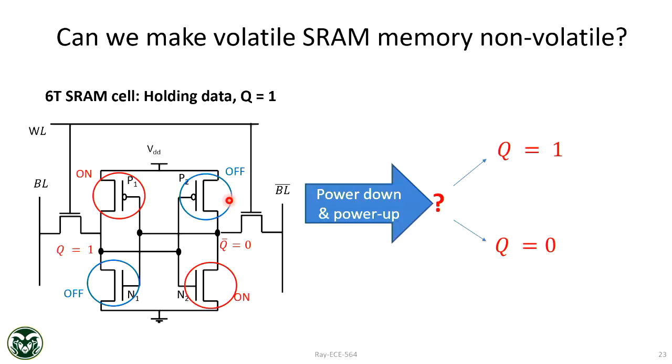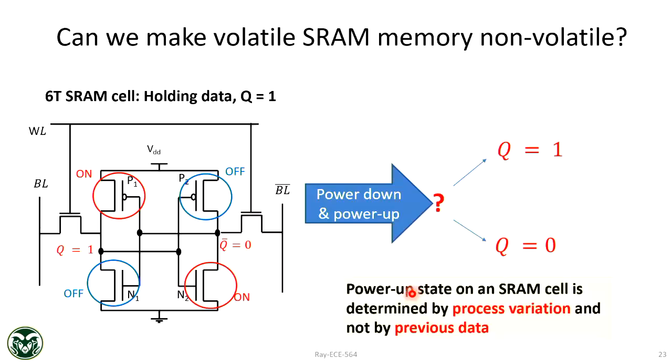The same hardware, you can use it for read-only type of memory using the power up state, because if you engineer it properly, it will always be there. Anytime you need to read, just power it up and read the uninitialized value. But it will also be acting like a volatile memory. Anytime you want to write, you write it. But if you want to know what is the non-volatile component, you just power it up. Okay, so there are techniques to do that. And if you're interested in this topic, I can share some of my papers and other papers as well on this.